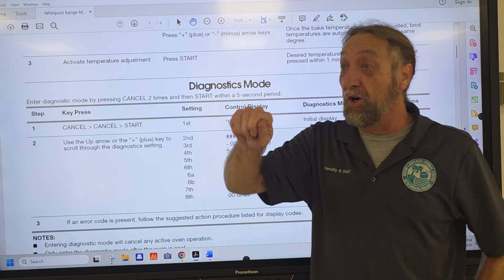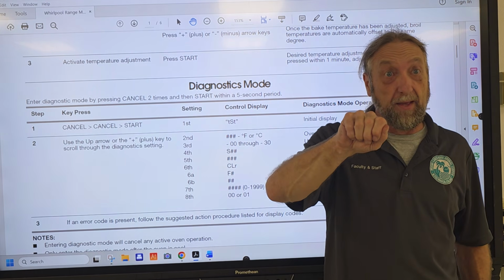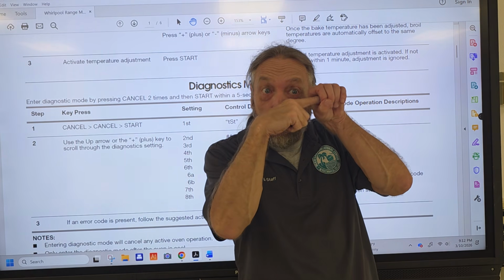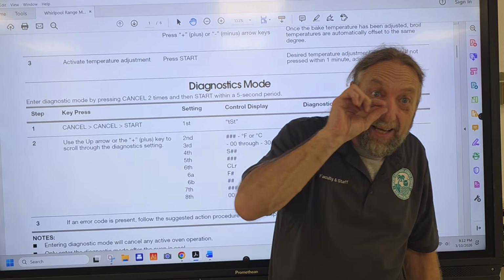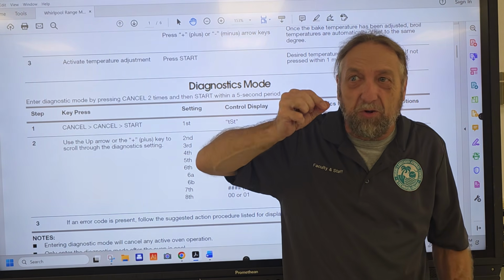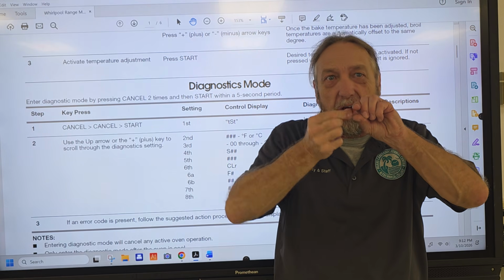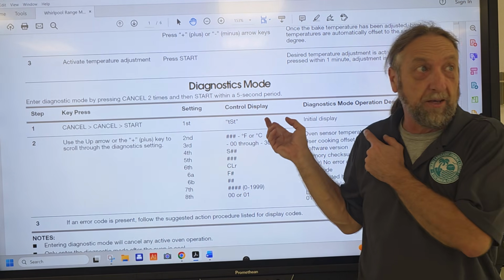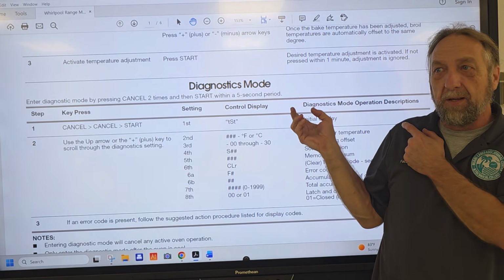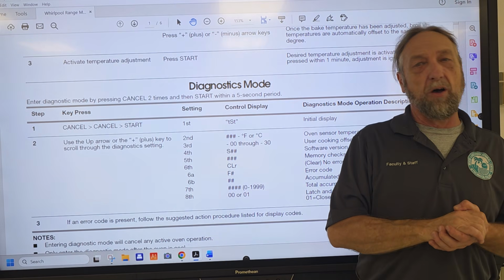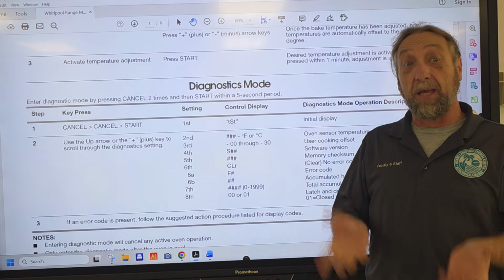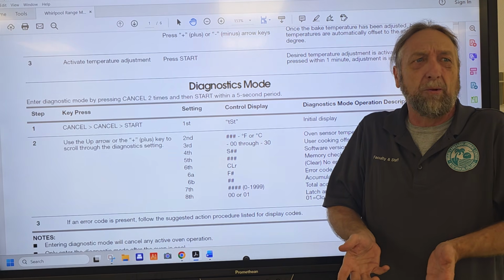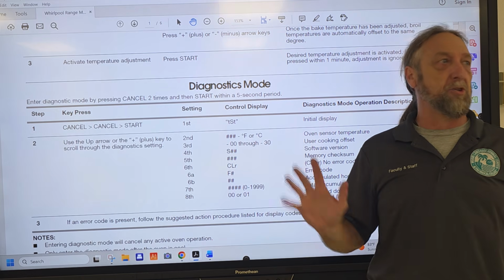Back in the day when you had a thermostat, you could turn a dial. They used to have the shaft that the knob went on, there's a hole in the shaft and there's a little screw in there, and you could get a little tiny screwdriver, like an eyeglass screwdriver, and you could turn the screw, but you had to hold the shaft and you could adjust it one way or the other. And that's how we calibrated the old mechanical kinds of thermostats before we went to this one. All right? But usually we say, listen, if that temperature's off, don't calibrate it. Because that's a mechanical device and it's already 20 degrees off. So you want to change? Even if you calibrate it, it's going bad, just change it.